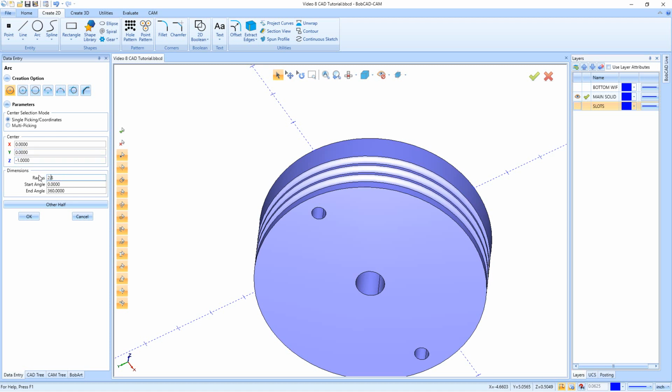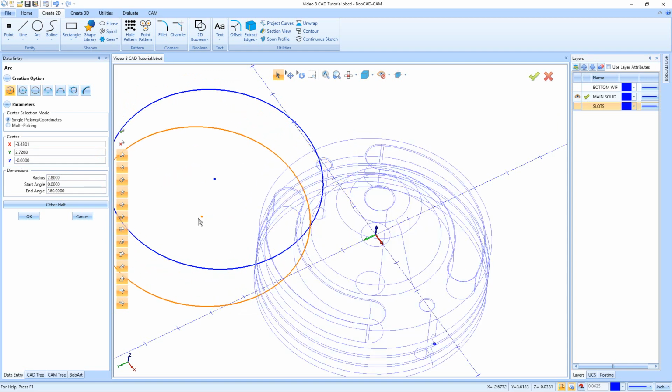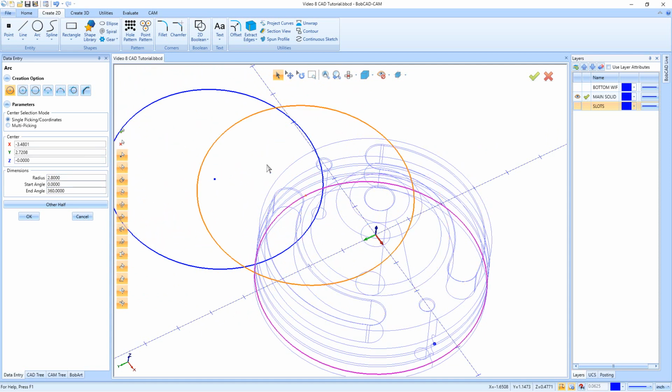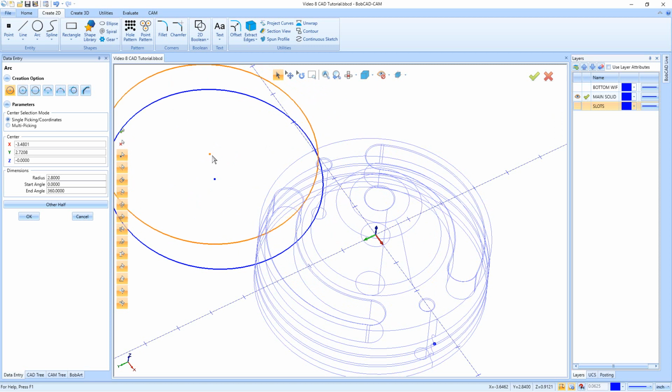Now you can't see what's happening right now, but if you click out of this box and you just click in here for a second, you can then hit the letter S. So when I hit the letter S, it hides the shading. But now since I clicked in the window, I have a preview. But you'll notice it's a darker color blue than anything else on the drawing. And the reason for that is because it's an editable feature right now.